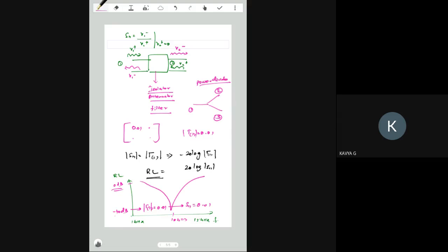Practically it is not possible to get 0. No device will ideally work in the microwave. There will always be a small mismatch, so a small reflected voltage will come back to the input itself. It is not huge. If you send 5 volts, in the practical case you may get some 0.01 millivolt like that in the reflection. Those are the practical values. More than minus 15 dB return loss is reasonably good, you can go with that. So this is a more practical aspect of seeing S parameter S11.